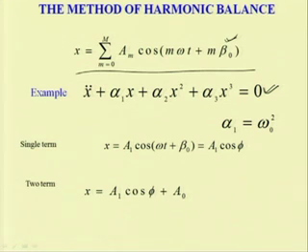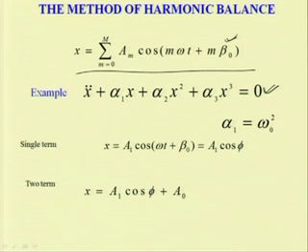The disadvantage of this harmonic balance method is that one has to know the solution a priori, or up to what order one has to take; one should have an idea. But in case of method of multiple scale, one need not know the solution a priori. And one more advantage of method of multiple scale over the method of harmonic balance is that one can study the stability of the systems by taking the reduced equation.